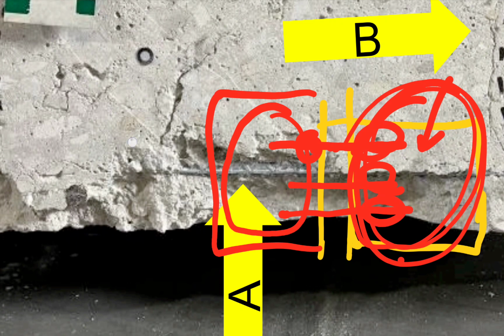I did see fractures, a couple of them come up to the brick wall. Can't see through the brick wall, but I must assume they're going past it. The brick wall's a veneer, so my assumption, the price of admission, is we remove part of this brick and literally look to see if the fracture is continuous. Internally, we look also, but out here is for free, removing a couple of bricks and putting them back for pointing. That's for free.